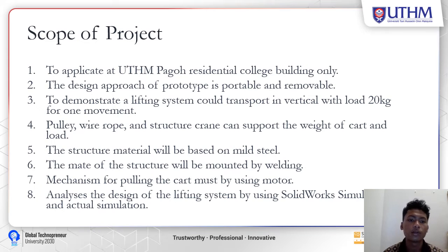There are 8 scopes of the project. First is to apply it at the student Hitachi Pagoh Residential College building only. Second, the design approach of the prototype is portable and removable. Third is to demonstrate a lifting system that can transport vertically with a load up to 20 kg for one movement. Fourth, a pulley, wire rope and structure crane can support the weight of the cart and load.